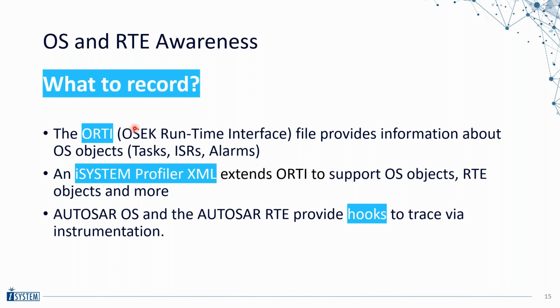That ORTI file contains information about how to trace tasks and how to trace ISRs, alarms, and other OS objects. So by providing that ORTI file to winIDEA, we can configure a trace so that we can record task states and the currently active ISR.